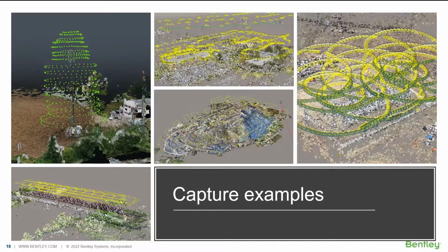If you do bridges, for example, that is also quite complex, because in the photos from a bridge you quite often get sky and water. If you go low and shoot under the bridge, you face the camera up, so you see a lot of sky in the photo. It's really hard to stitch together. But if you go too far down, you see a lot of water in it. It's also difficult for stitching photos together. So there's a certain flying pattern, and we really have to cover that well. We see really good results from our users on how to capture bridges and also all the other objects.